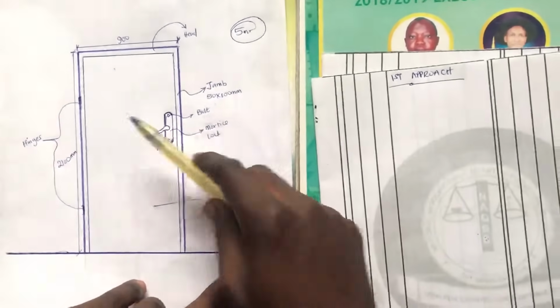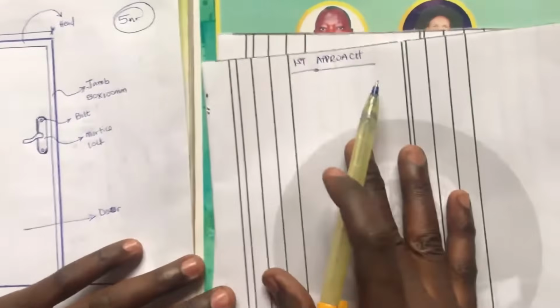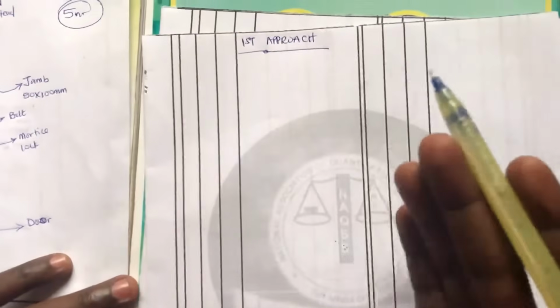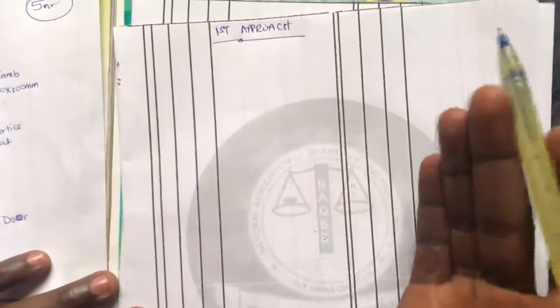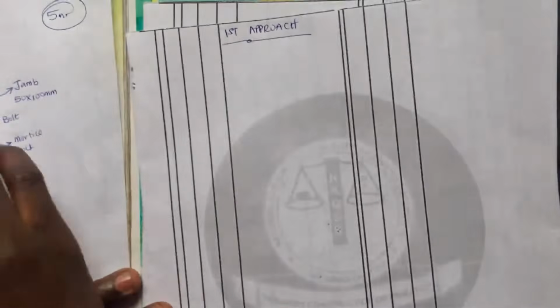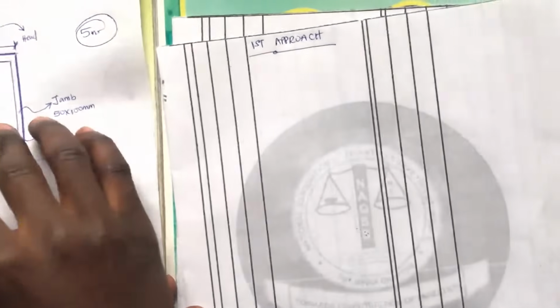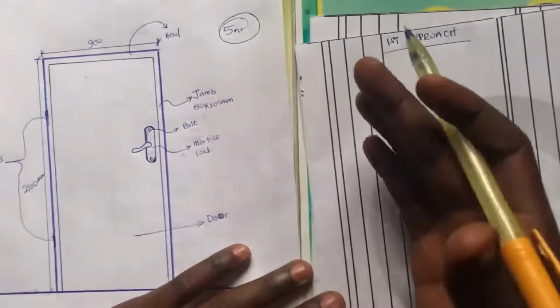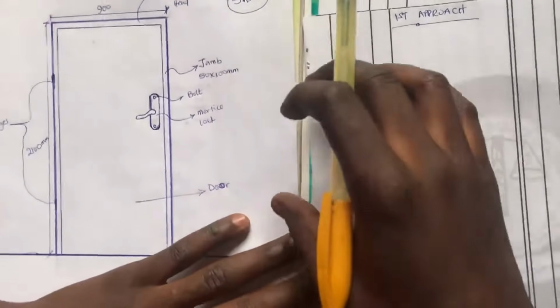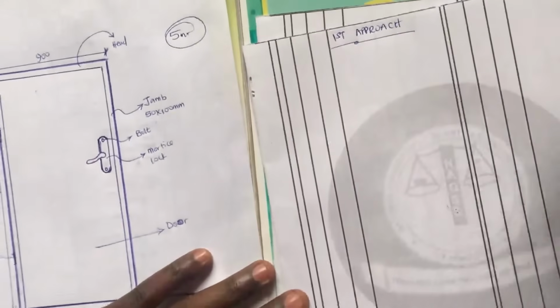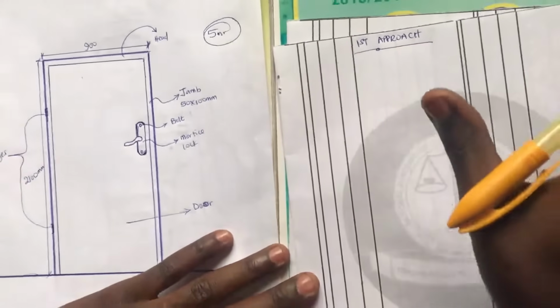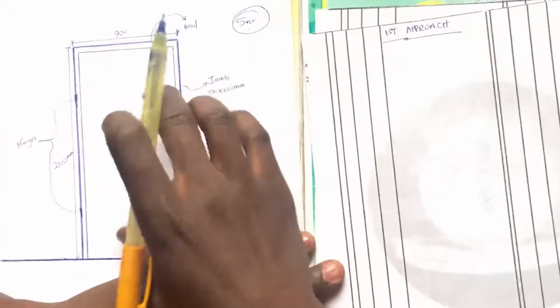If I'm going to make any provision for this door, it means I'll be providing about 500,000 naira for 5 of these doors. So the first approach, which is what we usually use in our normal projects, or in real life projects, is that I'm going to provide the sum of 500,000 naira for the purchase and the supply of this door to site. And that is what we refer to as the PC sum, when you allocate a particular amount of money to a subcontractor who is specialized in one field in construction. So the subcontractor is the supplier of the door.